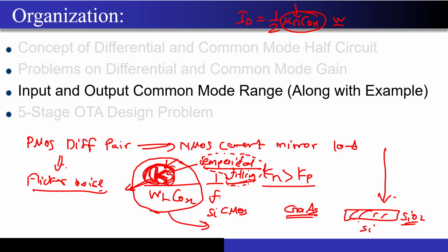That means the way TSMC fabricates the oxide to semiconductor interface, and the way UMC or GlobalFoundries fabricates it, will differ. If TSMC's oxide interface is very, very pure, the flicker noise you get in TSMC's MOSFET will be lower than what you may get in UMC's or GlobalFoundries' MOSFET, correct? This K is basically telling you the quality of the silicon to silicon dioxide interface, correct?